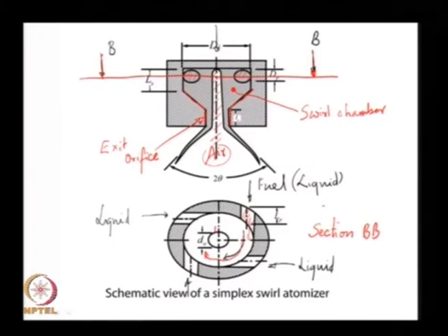We will come to the ratio of the two velocities in a moment, but essentially I have created a very high swirl velocity of this liquid, and that high swirl velocity causes a low pressure region in the center line, causing this air to be drawn in. So, there is a low pressure there, okay, just like a spinning bucket. If I take a bucket, I start with a meniscus, if I spin it around the center line, I spread this out into a parabola.